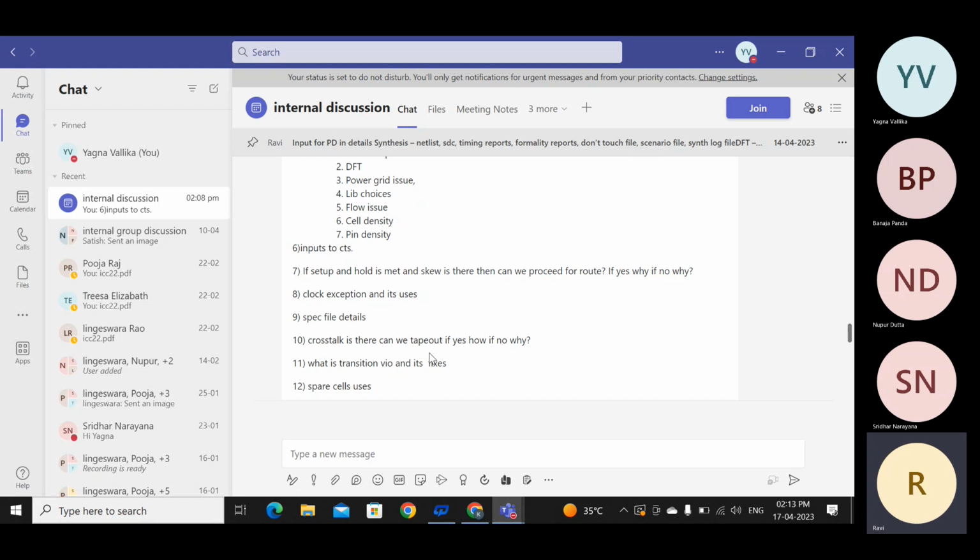So these three aspects, the buffer levels, the net delay, and the cell delay, should be relatively similar. Buffer levels would be the same whether it is slow corner or fast corner, but you should also look at the cell delays and net delays in the fast corner and slow corner and do a comparison, so that the net delay is not compensated with cell delay in one corner, which would actually make for bad balancing across corners, and that would impact your quality of timing. Okay.